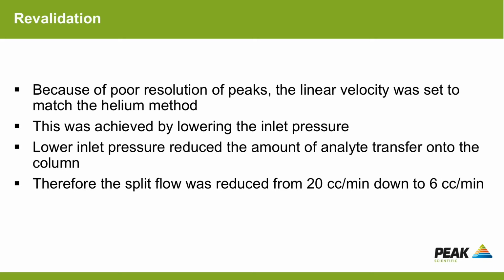An alternative to this would be to use pulsed pressure injection, and this can be a way of improving the transfer of the sample onto the column when using hydrogen, and preventing reaction between hydrogen carrier gas and your analytes. But in this case, because there was a high enough split ratio, the split flow was reduced.